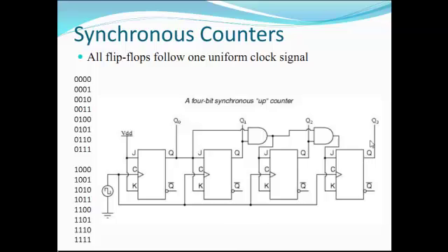The same applies for Q3. This works because if we look at this binary counting system again, this third least significant bit, for example, only switches when all the less significant bits are 1. In the next signal, these bits will change back to 0, and this third bit will change to 1. This pattern also applies to other more significant bits, such as the fourth, here.